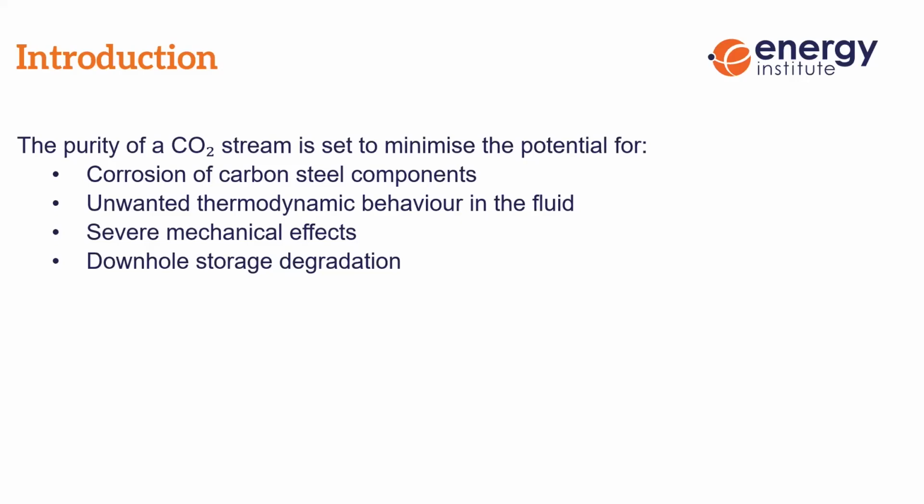The impurities can lead to unwanted thermodynamic behavior in this fluid, because the CO2 stream can change very rapidly between gas phase and some sort of intermediate phase, which is between gas and dense phase, and of course in and out of dense phase. And the density changes are very large and difficult to control.